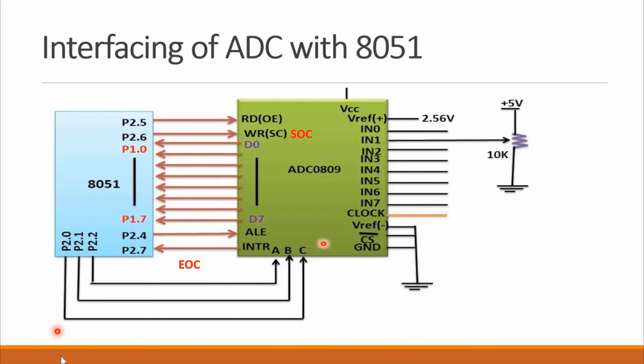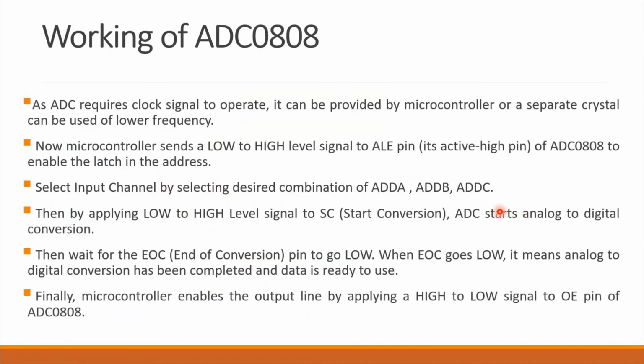You will have to connect 3 to 4 flip-flops which will provide the reduced clock that can be given to the ADC. But that becomes complicated, so that's why I have not shown it. Here you can directly write it as an external clock. So see here, I have provided you the steps.